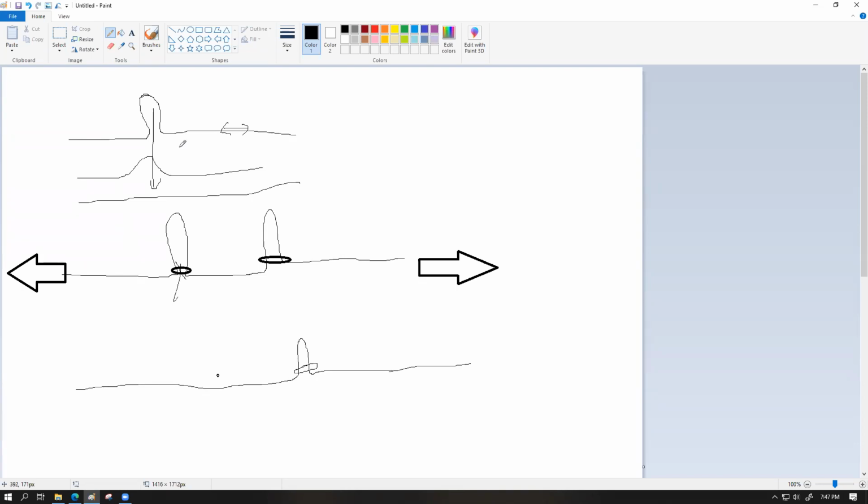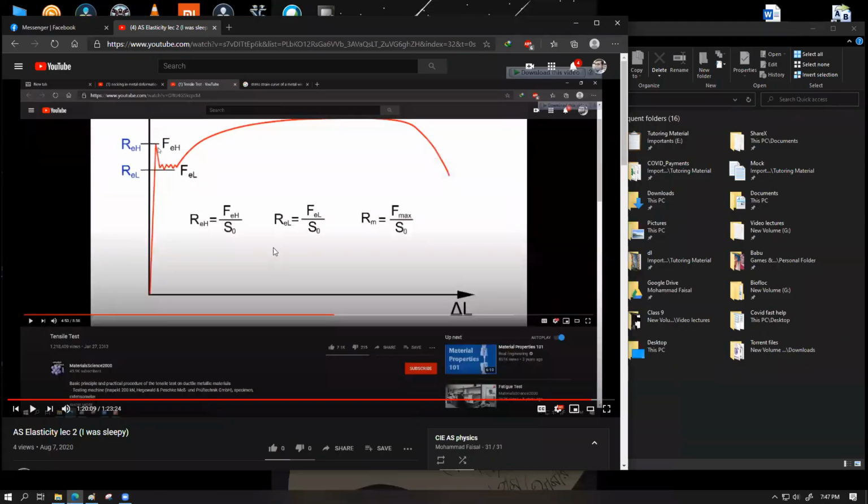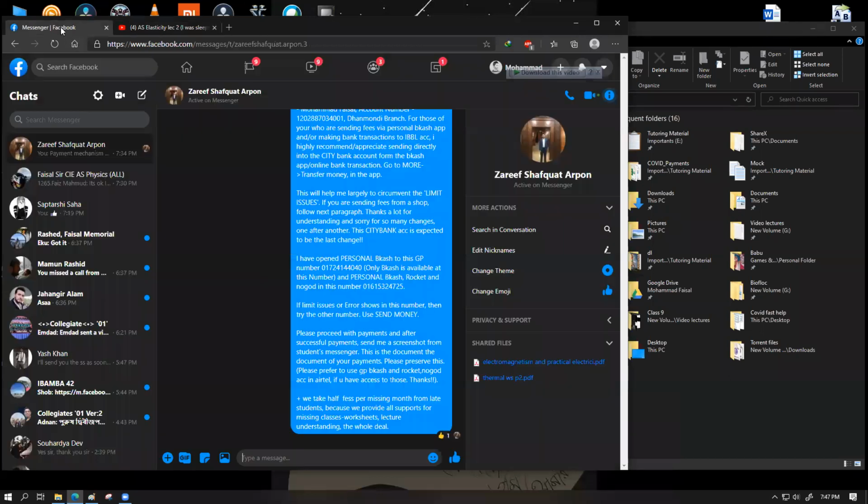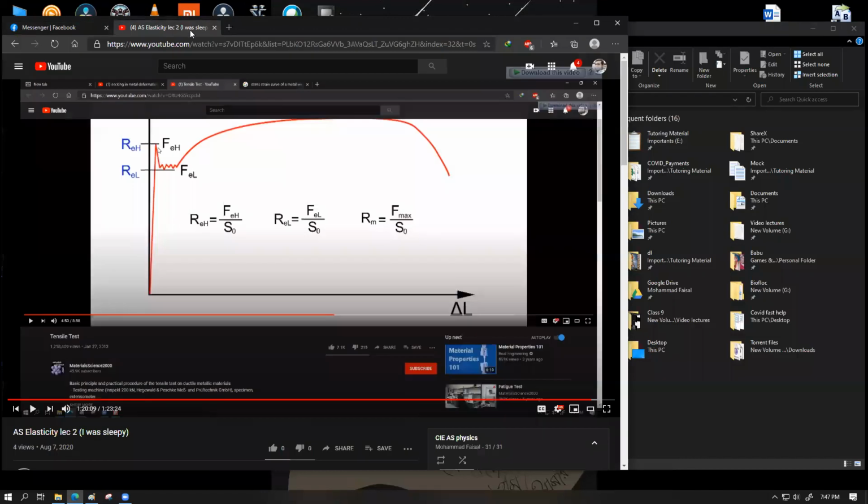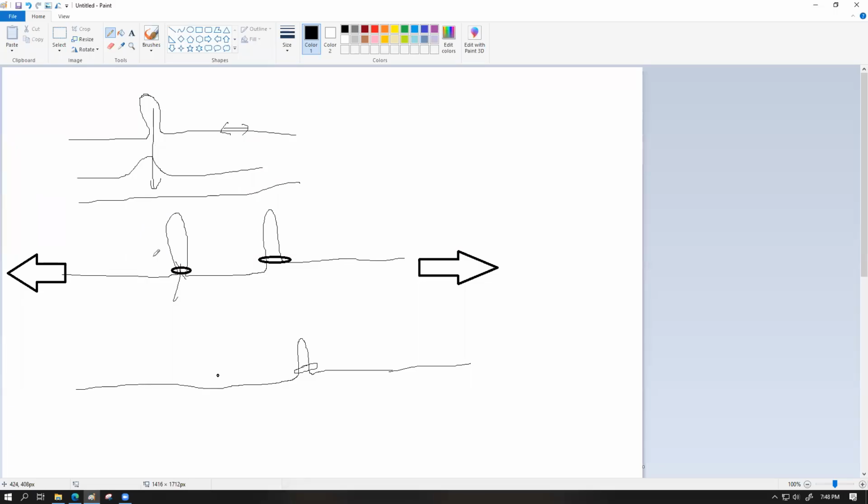Well, for a small duration, it would be that much. What I'm trying to say is that if we plotted this with respect to time, at the instant whenever these loops did break down, if we plotted this force with respect to time, at the instant whenever these small internal breakings happen within the material specimen, it would be possible that we might see the force dropping to a minimum. Maybe a highly magnified value could also give you 0, then it spikes up to the highest value once again. With every single internal breakdown, I'm not talking about splitting apart, I'm talking about small microscopic cracks being produced in the atomic structure of the metal specimen.